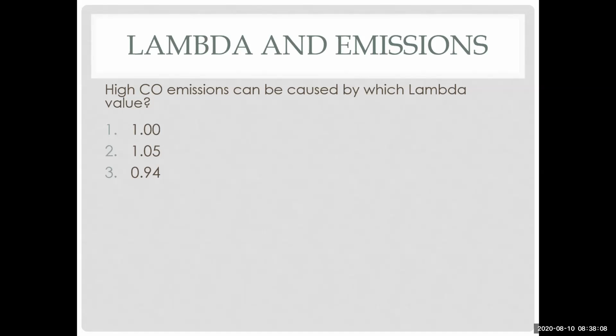But carbon monoxide, 14.7 is a maximum or minimum at that time? What do you mean maximum or minimum? The lambda is 1, which is a normal operating range. Right. And at that time air is 14.7. So the carbon monoxide existing is the lowest? Yeah, well, it's not going to be the lowest. It'll get a little bit lower as we go lean, but it is manageable.